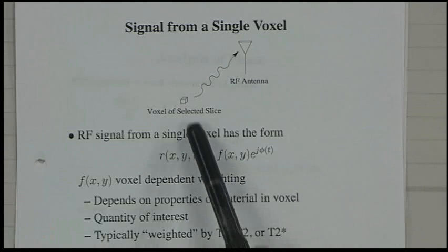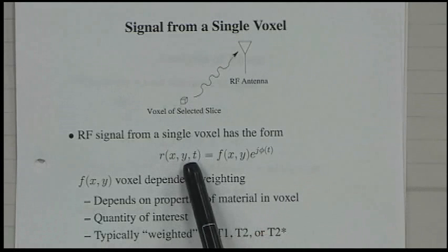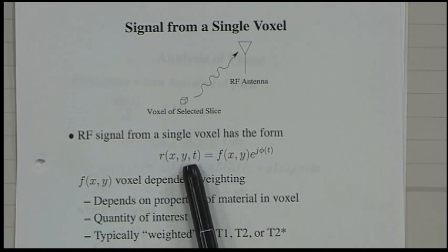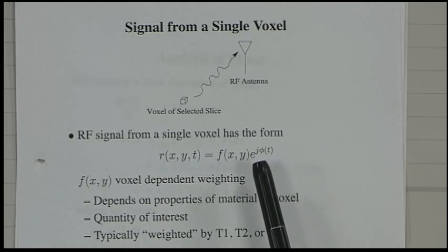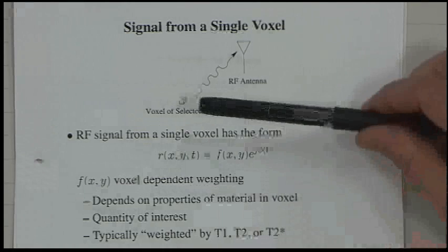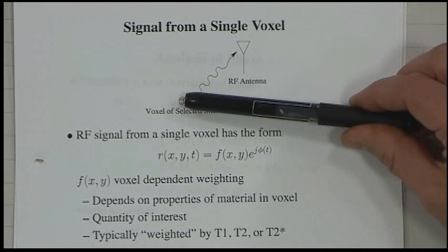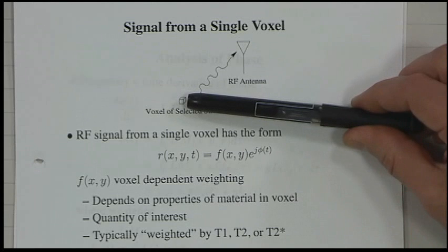Okay, so for this particular voxel, here we don't have Z anymore. We didn't have Z before because I had an error in the notes, but there's not supposed to be a Z here because now we're restricting ourselves to just that one slice. At this XY position we don't change the gradient in Z. We leave that alone, okay? And now we just shift the gradient in X and Y. By shifting the gradient in X and Y, we'll change the magnetic field strength at this point and thereby change the frequency of oscillation, okay?